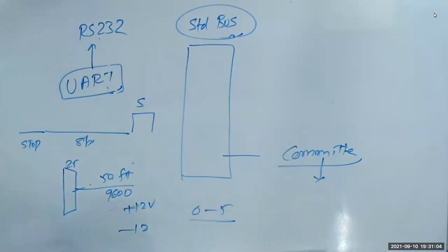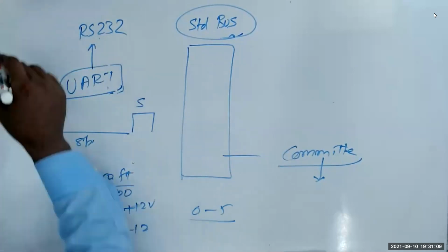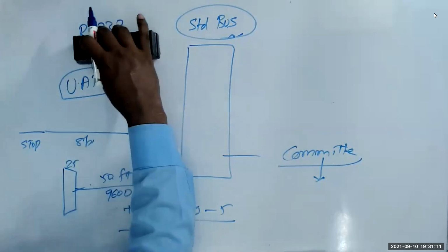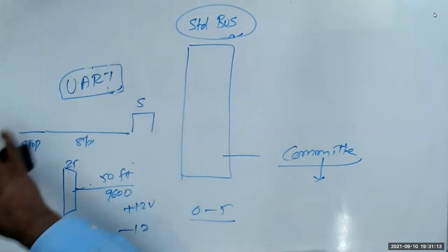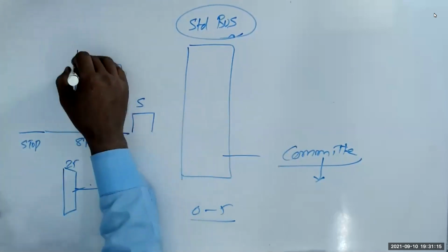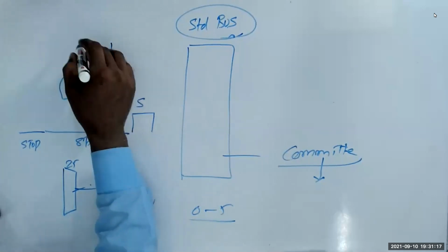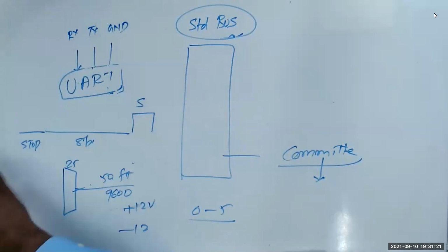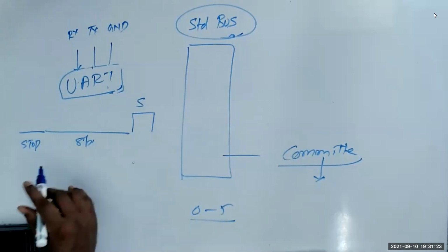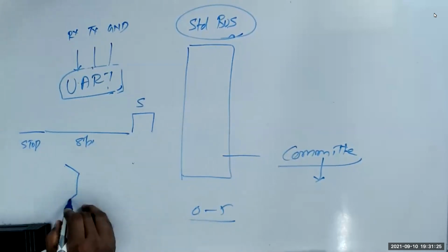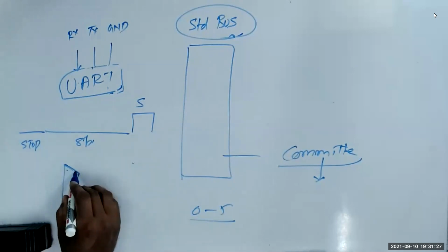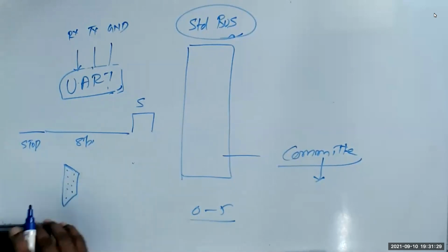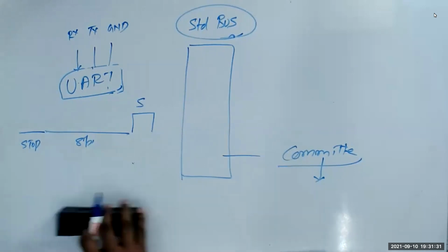But what happened, as we discussed, is that RS-232 died, and we don't use it now, only very rarely. So finally UART came. UART takes only 3 pins: RX, TX, and ground. They brought the 25 pin connector down to a 9 pin connector. These are all hardware standards.